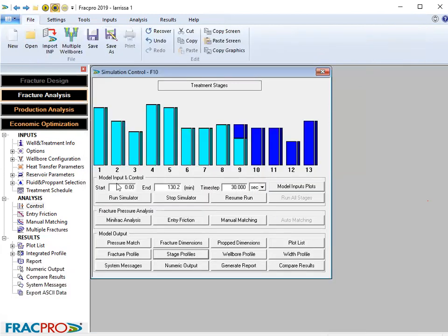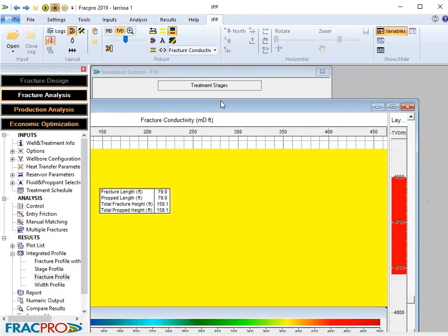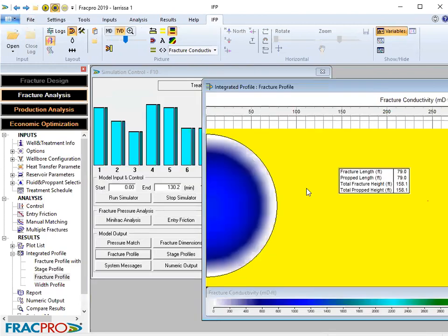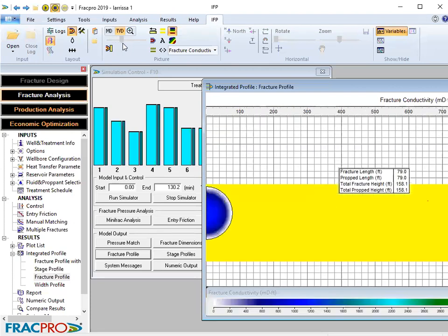Maybe I have to rerun the simulation. All right, I have to rerun it in 3D. Voila. Rerun in 3D. I look at the fracture profile. Okay, so that's exactly what we have. So that is the fracture profile in our zone that we are going to have. You can always reduce it, increase it. So this is our fracture profile that you're going to have.